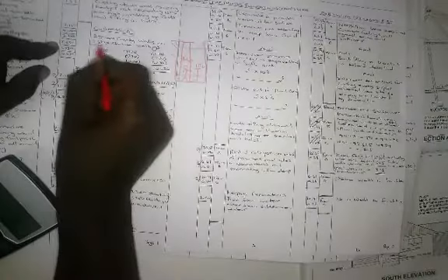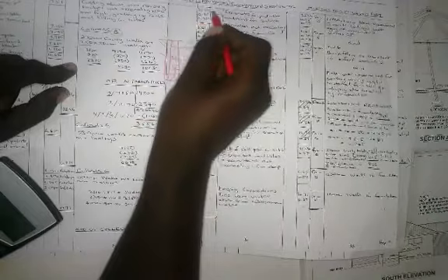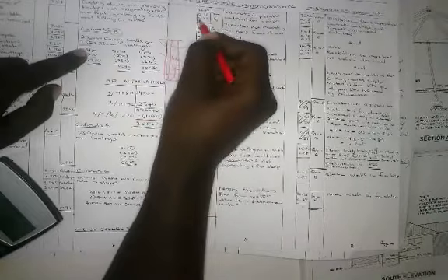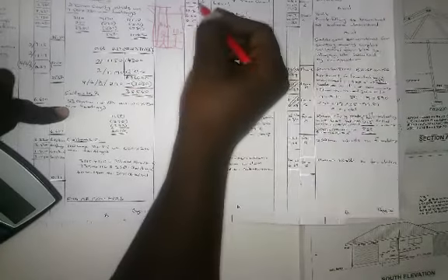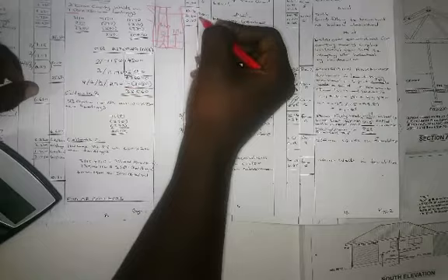I hope that is clear. So it's going to be 35.56, and then you come to A to find your information. At A, it gives you that the width of your footing is 750. Already your drawing tells you your depth is 800. So it's 35.56 times 0.75 times 0.8, and that is from A.